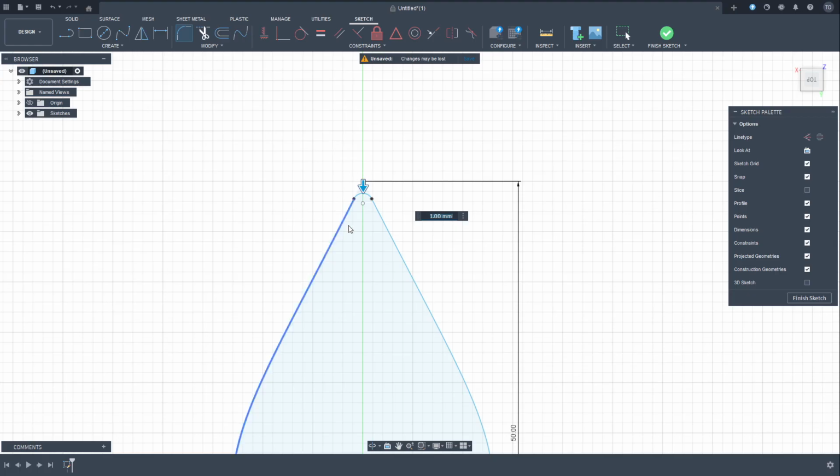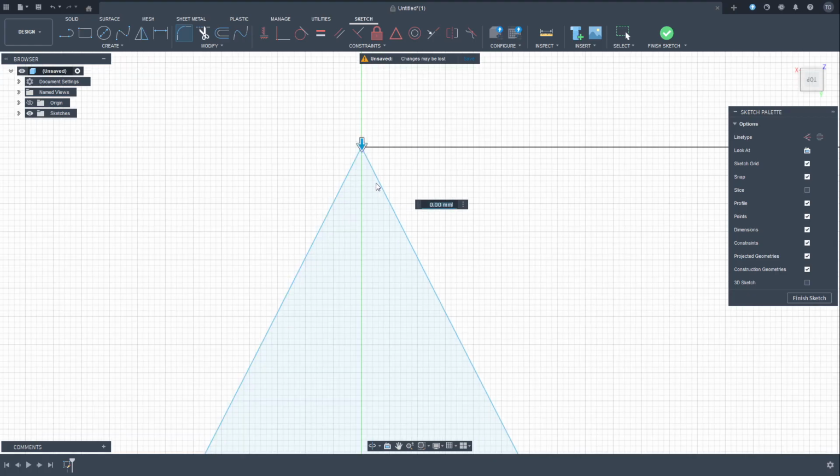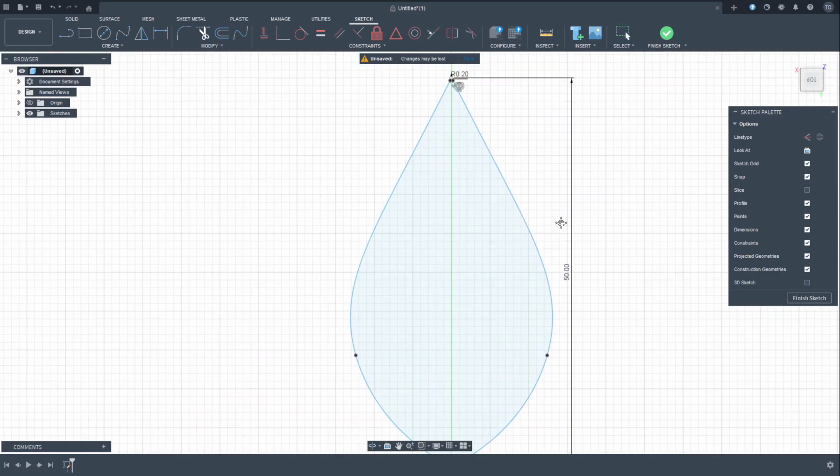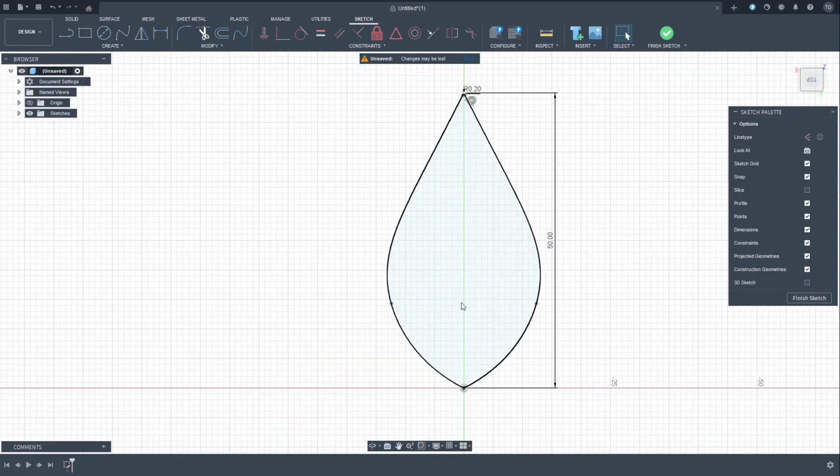The reason I'm doing this is because a very sharp turn in your clay cutter is not very good. Because when you cut your clay using this cutter, that sharp corner tends to stick in the cutter and break off. So that's why I give it a little bit of fillet, not much, just this much, and then hit enter. Okay, so now what we have is this teardrop of an earring. I would call it teardrop, whatever.